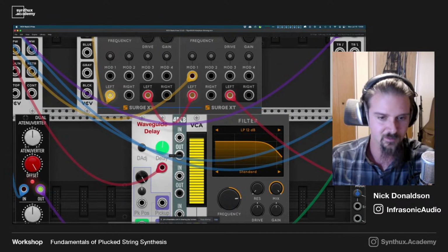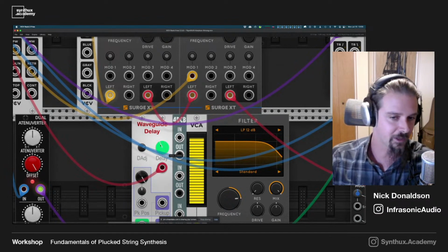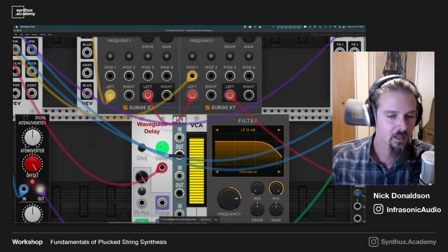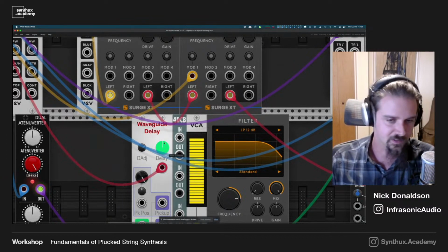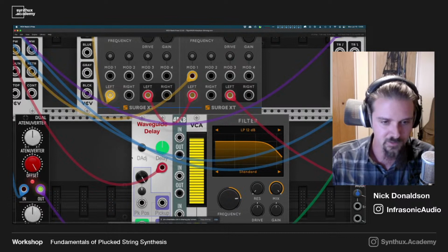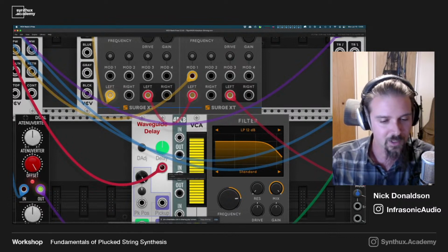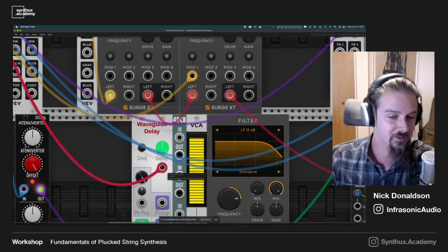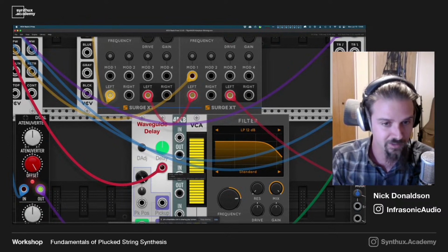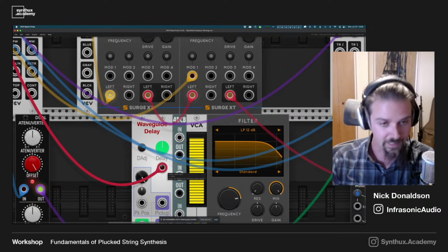This pitch just, so you can kind of tune it with whatever sort of offset you want to that. By default, it's just a C. It expects 0 volts as C, which is kind of the standard. But say we go from 1 volt to 2 volts, that's up 1 octave. We need to cut our delay time in half, because the shorter the delay time, the shorter the period of the fundamental wave that we're getting out of that.